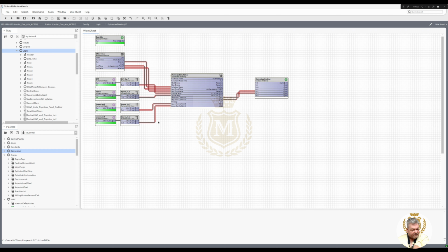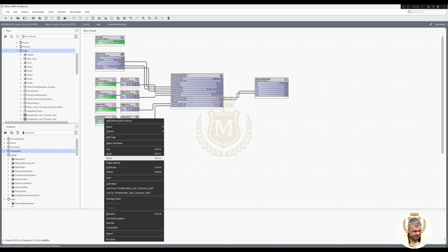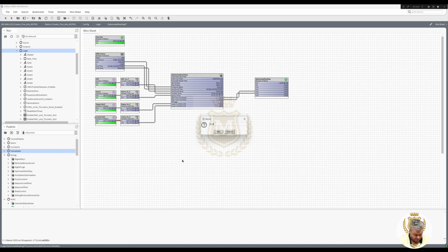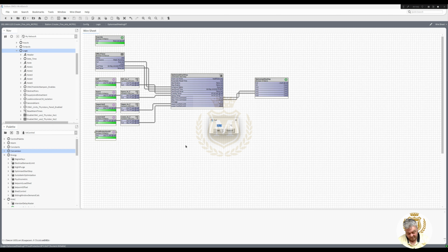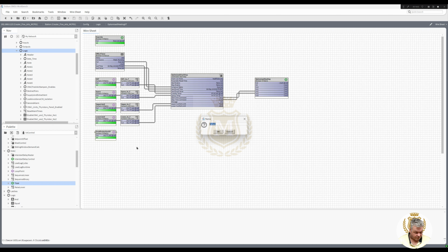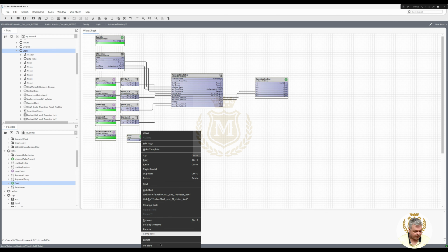The reason I'm leaving in 16 is I'm going to do frost protection. Let's do that now. Duplicate. So we'll set a frost protection set point. And if it goes below, I don't know, let's say 16 degrees, we can go into frost protection mode. So I'm going to put a T-stat in there now. So a T-stat, bring that across, put just frost there, expand the points.